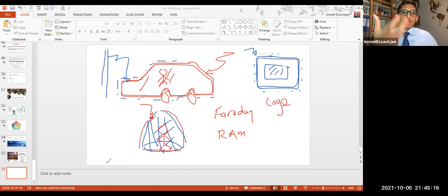You need to calculate the load, because you're constructing an installation to supply a specific load, in terms of watts and so on. And then you select, in a list of available cables or wires, the one which is closest. Then you need to look at the protection. What is the protection device you're going to use? This is going to affect the cable you choose as well. It can be a fuse, a circuit breaker and so on. There may be a change in the size of the wire you're using.